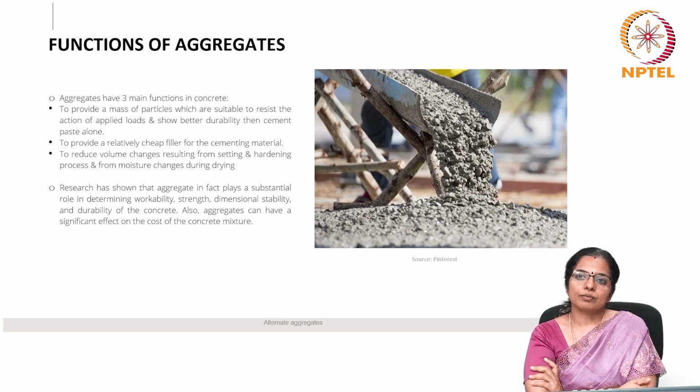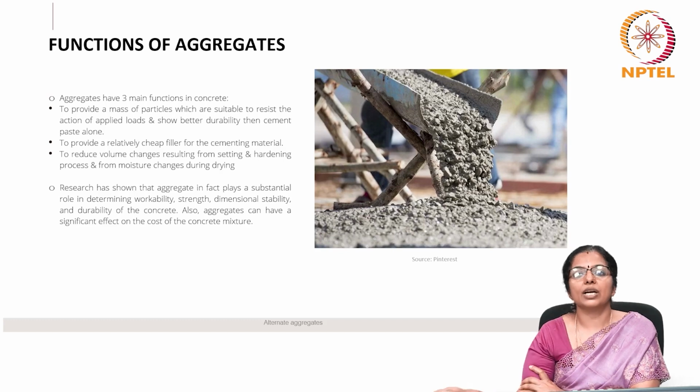Research has shown that aggregate in fact plays a substantial role in determining workability, strength, dimensional stability and durability of the concrete. Also, aggregates can have a significant effect on the cost of the concrete mixture.